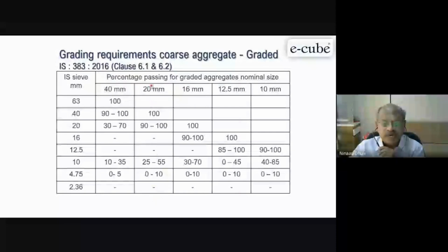So we are going for 20 mm. Here up to 10 mm is also there. So with a 10-20 combination we should have this. Generally, going to the site, people use 50-50%. So depending upon their particle size distribution, you check whether they are falling in this limit. This is a finer one, this is a coarser one.